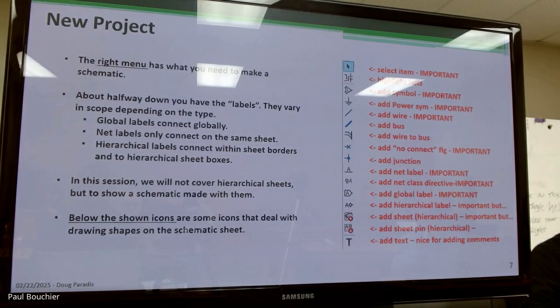When you have a pin that's not connected, you have to mark it as not connected. The reason for that is the ERC is going to expect it to go somewhere. And if you don't have it marked as non-connected, now nobody can call me out on that. ERC, electrical rules check. Okay, so that's one of the goals and one of the strengths of using a program like